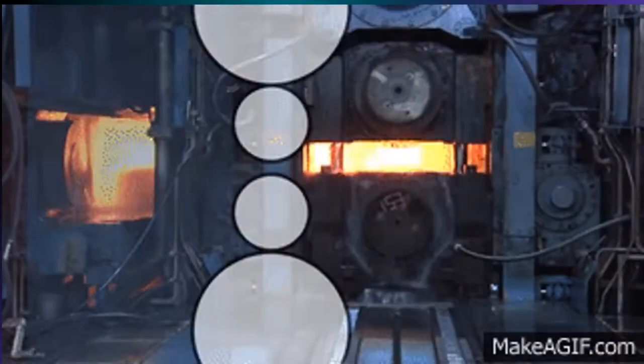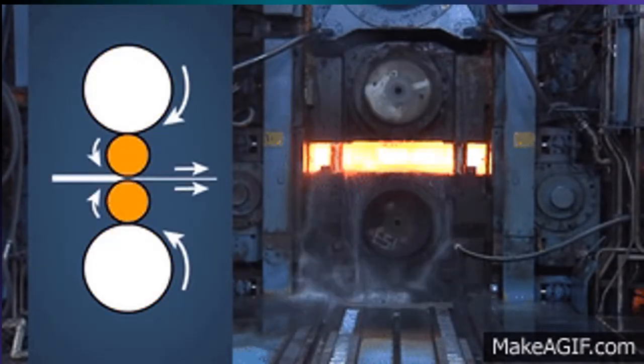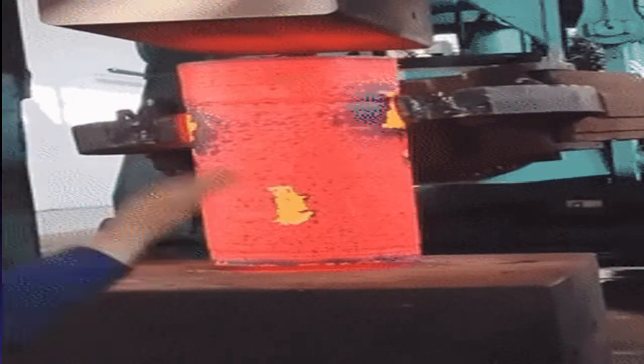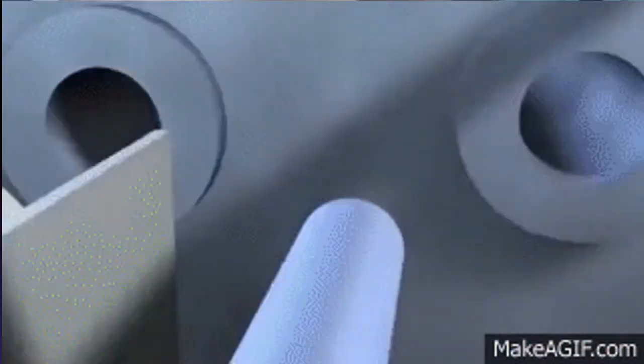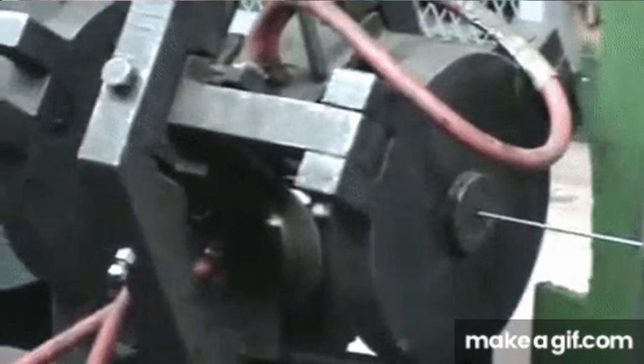The four basic bulk deformation processes are rolling, where the slab or plate is squeezed between two opposing rolls; forging, where the work is squeezed and shaped between opposing dies; extrusion, where the work is squeezed through a die opening, thereby taking the shape of the opening itself; and finally wire and bar drawing, where the diameter of the wire or bar is reduced by pulling through a die opening.